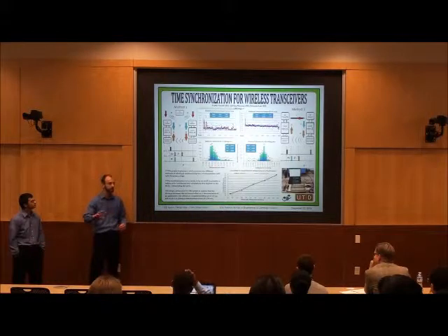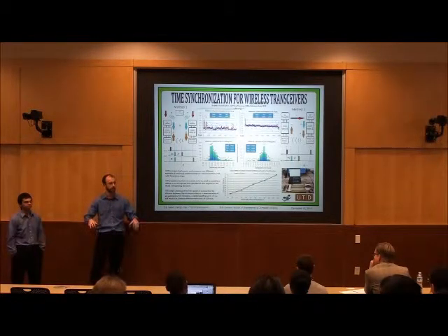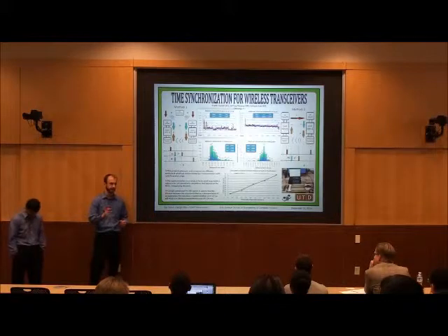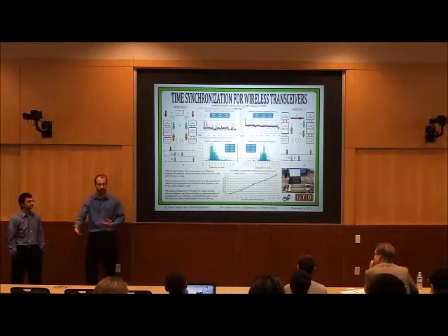The main problem our project addresses is the synchronization error, basically the difference in the received time reference from these two microcontrollers. Depending on your synchronization error, that is ultimately going to introduce either a little bit of error into, in our case, the distance measurements, or a lot of error.